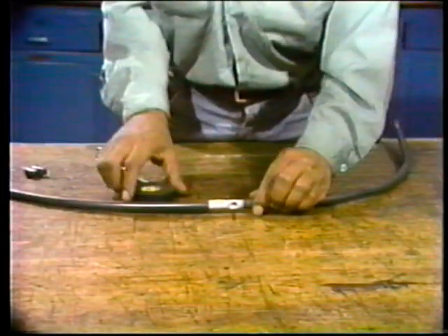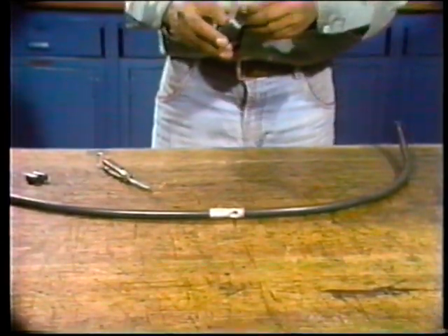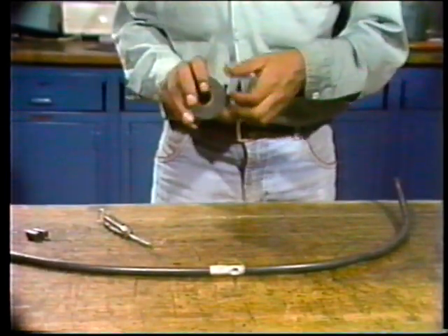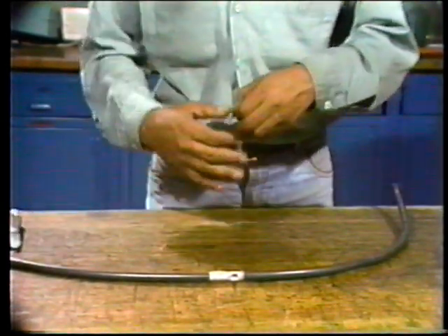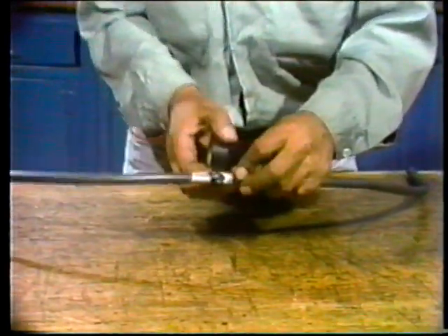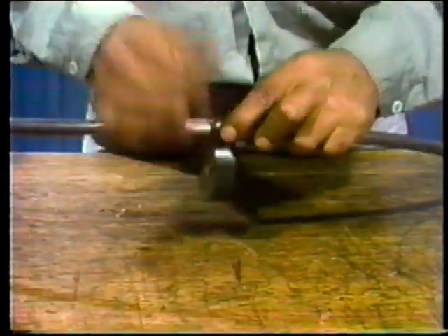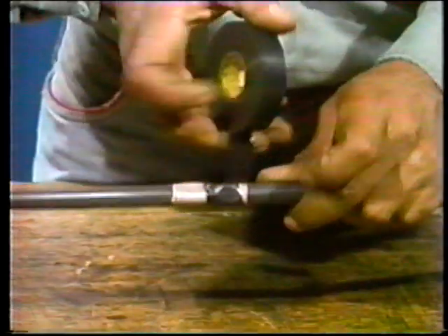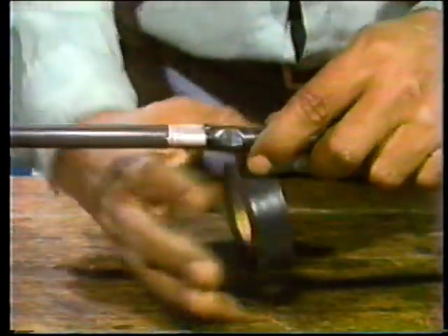The information on the box also lists the types of insulation the tape can be used with. Bill is working with type TW, and that's on the list, so he can be sure the tape is compatible with the original insulation. Okay, Bill's going to tape the splice now. His objective is to tape the splice well enough to duplicate or exceed the quality of the original insulation. The tape has to provide strong electrical protection and mechanical protection when he's done.